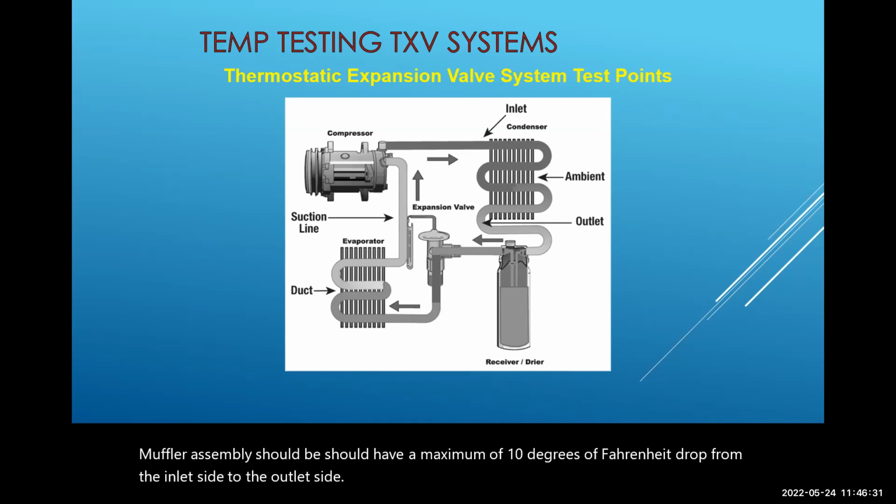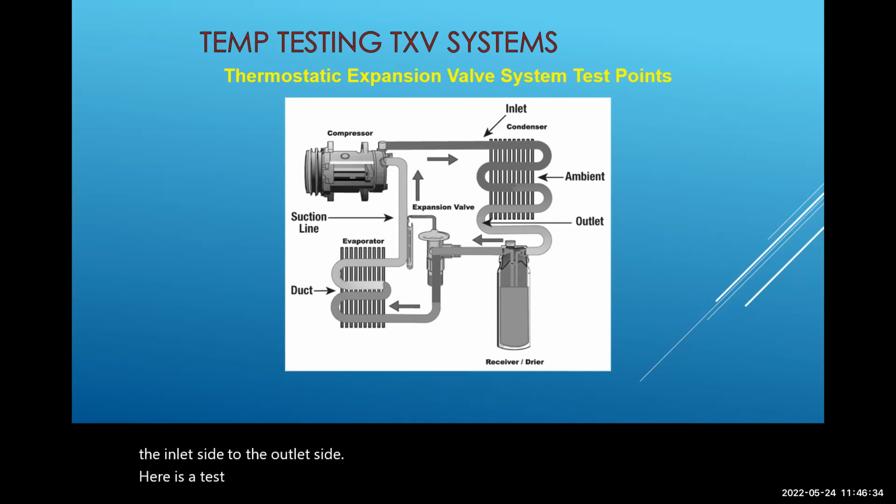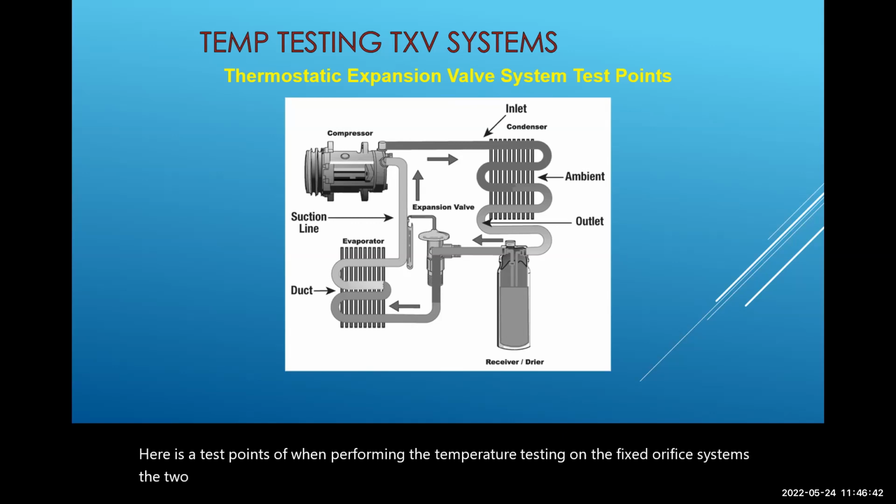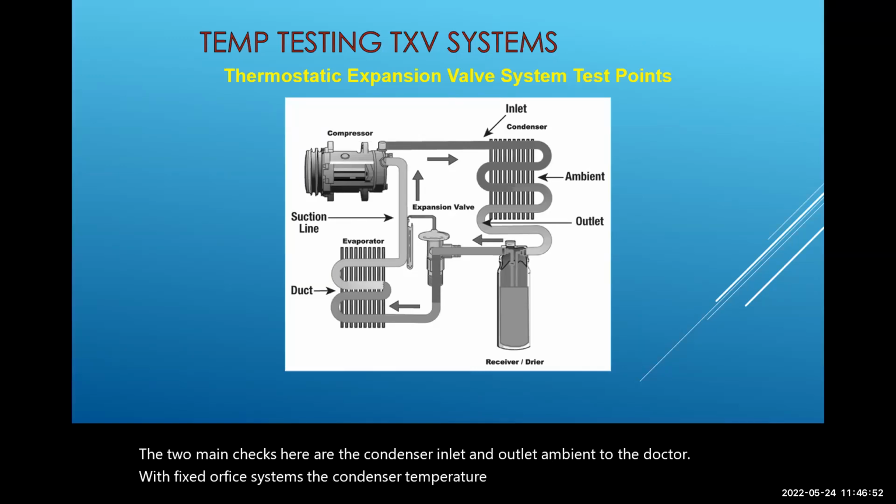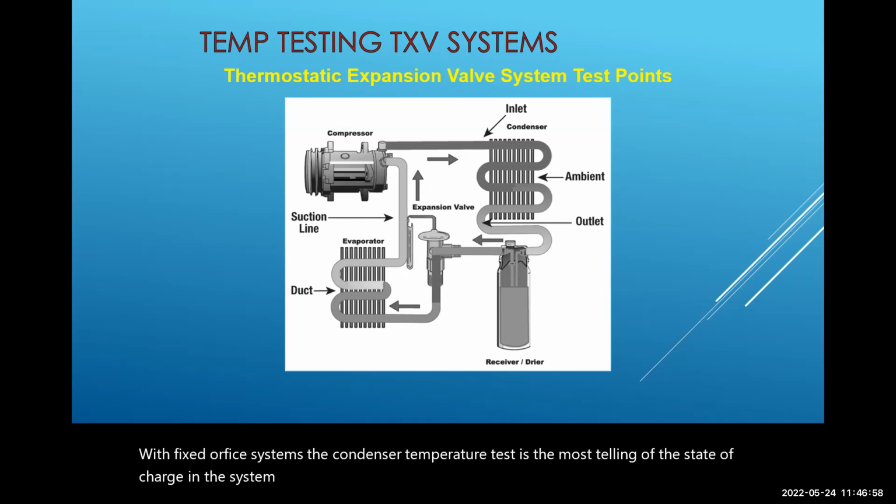Here are the test points when performing the temperature testing on fixed orifice systems. The 2 main checks here are the condenser inlet and outlet, and ambient to the duct. With fixed orifice systems, the condenser temperature test is the most telling of the state of charge in the system. So like I said, I always like to look at the actual temperature drop from the inlet of the condenser to the outlet of the condenser.